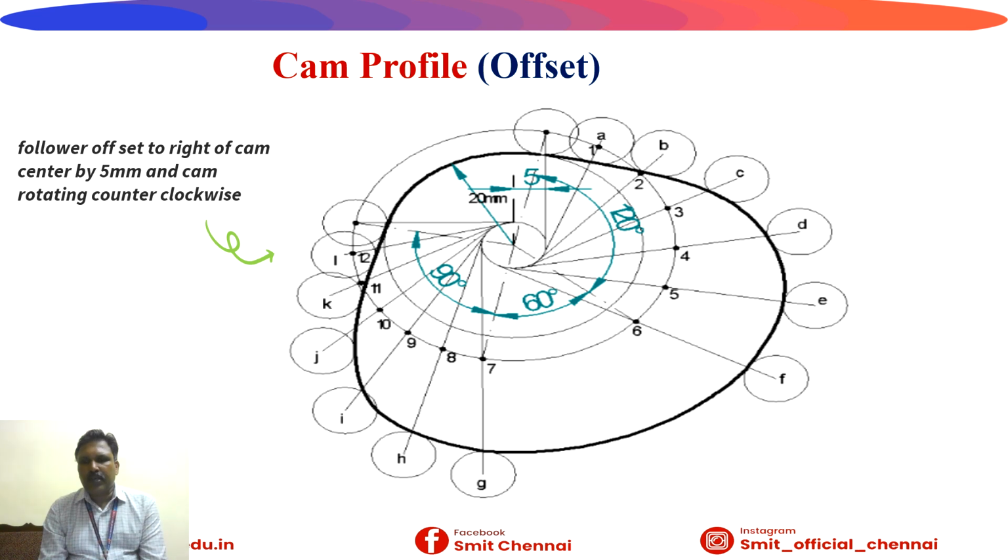Then again, with the help of scale and pencil, we have to draw the tangent lines to the offset circle. In the previous first case, there is no need to draw the tangent lines because there is no offset condition. In this offset condition, you have to draw the tangent lines, and the same procedure will be followed. We have to take the distance from the displacement diagram and take the intersection arc, and finally join all the points with the help of the pencil, joining with the base circle. The curve should not enter into the circle. That is important. Finally, you will get the cam profile.